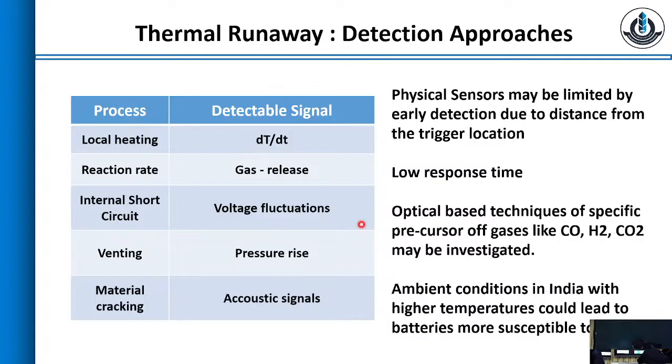We came to know it was heating because we were just keeping our hand on the platform and realized the heat. Ventilation is there, but it started overheating. After some time, we changed the battery. That is again happening because some kind of internal resistance is increasing, and that is leading to high heat.